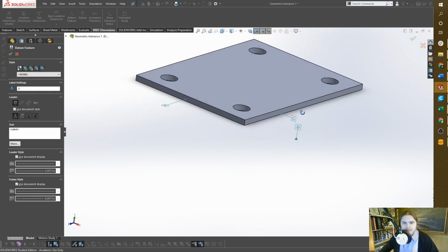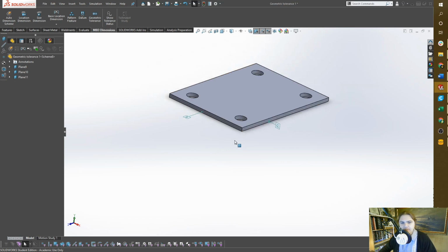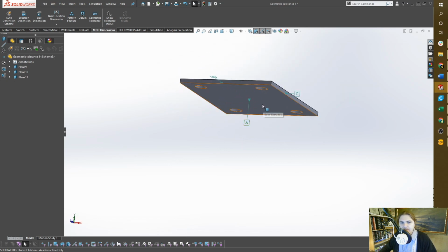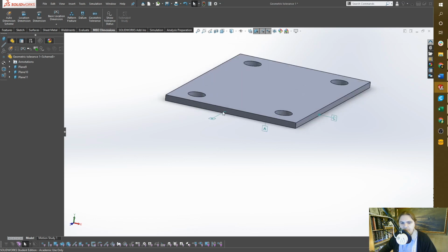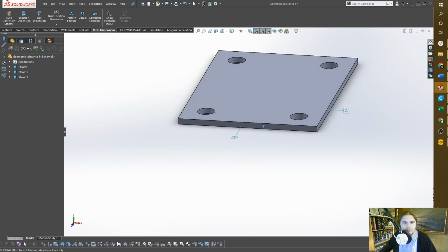So if this was placed into a datum reference frame, or to test the part or to measure it to make sure it's within specification, they'd place it on the A datum first, then the B, and then the C. And then from there they would be able to measure the part consistently from piece to piece.